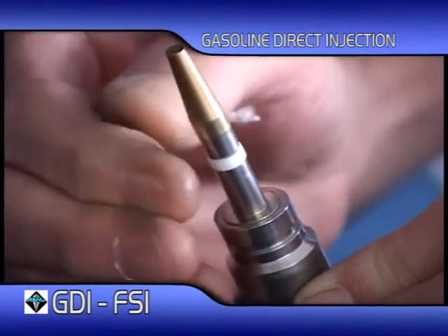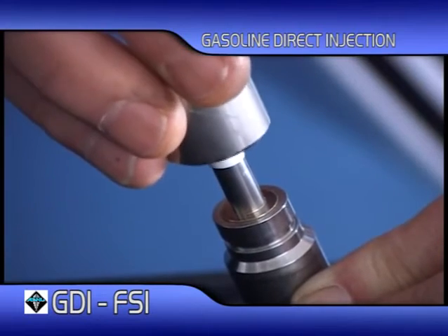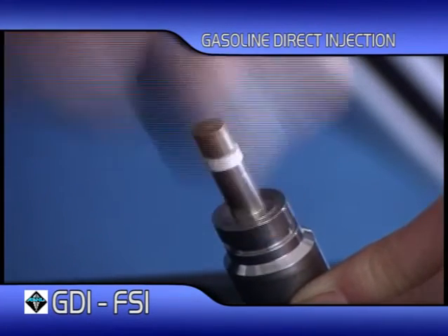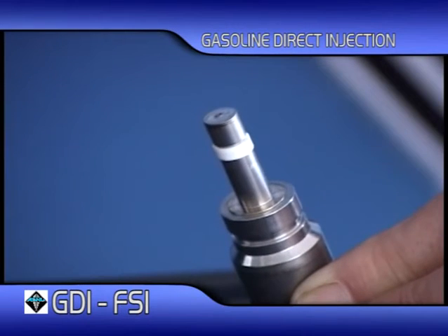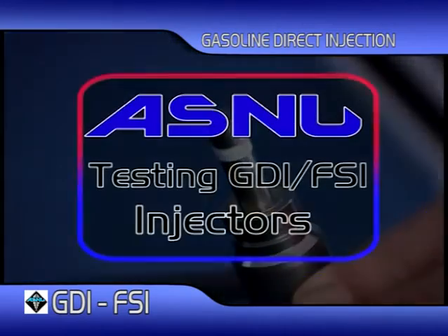To complete the fitting, the seal needs compressing to its correct size using the sealing ring compression block. The injector is now ready for retesting. If all injectors are performing to an acceptable level, they can be refitted. Any injectors not meeting the required performance must be replaced.